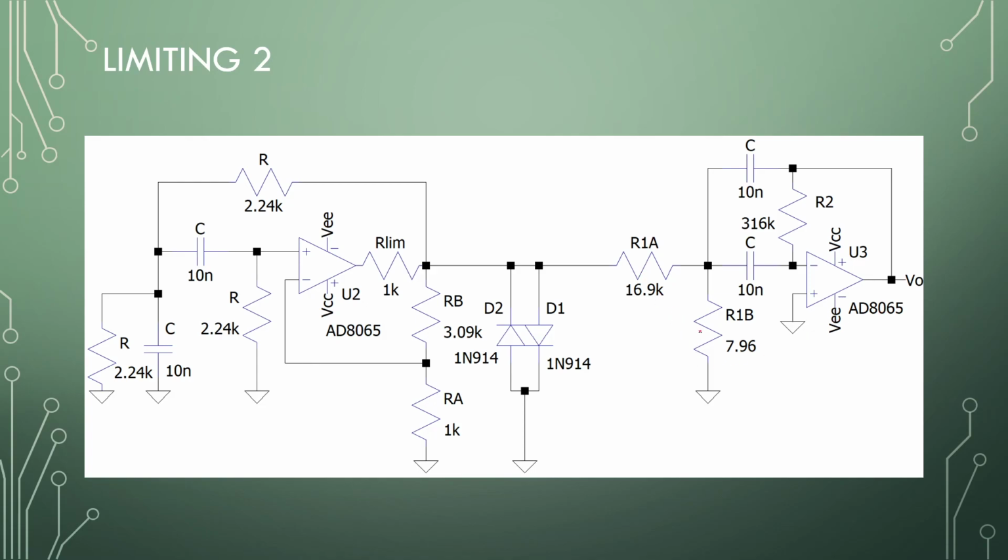Okay, so these resistor values here are to correct the gain, so 700 millivolts to 5 volts, and the capacitors and the resistor values are for the Q factor selection and the center frequency at 10 kilohertz. So these are two bandpass filters, different kinds, designed for the same frequency, but this one is pushed to oscillate, and this one will not really oscillate. So let's jump over to the simulations and let me show you these two circuits working.